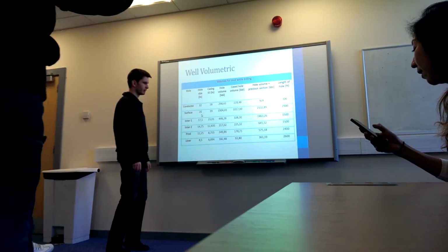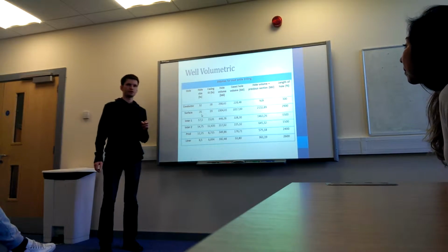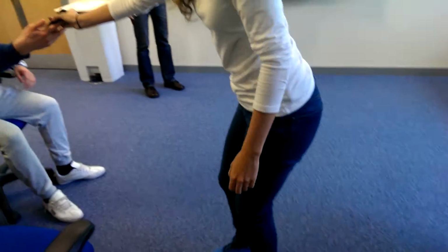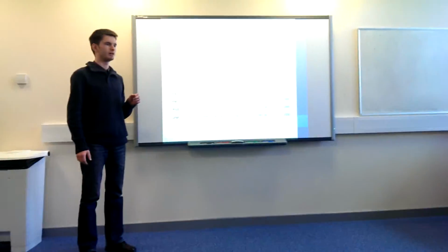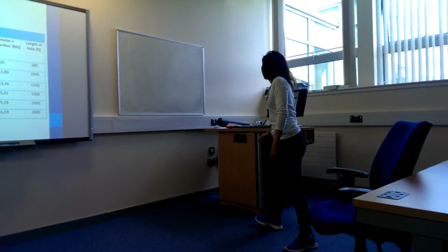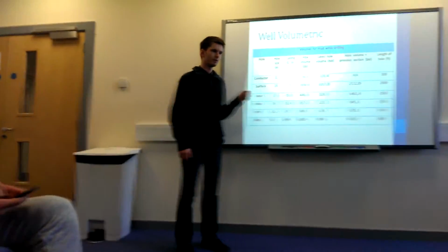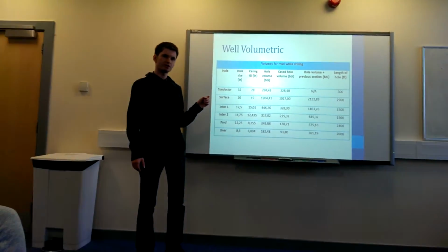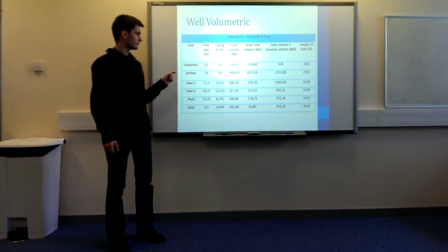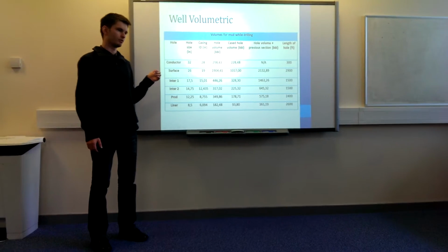I'm going to continue Kingsley's presentation. My topic was mud selection and cementing program. The idea was to start by relating the maximum amounts of mud required during the entire program. An approach which I used was to calculate the amounts of mud in each separate section. You can carry on with these calculations for open hole volume, including the previous one, cased hole volume.